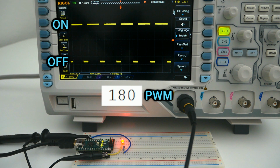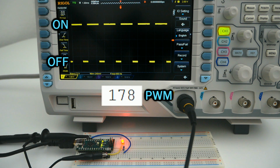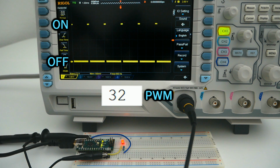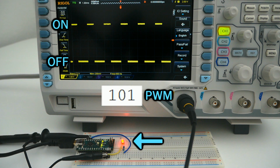For most Arduino boards, the analog write can be any value between 0 and 255. 0 means the pin is going to be off, and 255 means the pin is going to be fully on. Any value in between will have intermediate states that, for example, in an LED will just change the brightness.